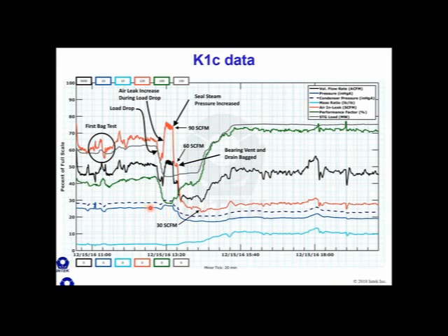And here in the blue line, you can see is their condenser pressure. It decreases as the air in-leakage decreases. You can also see that we've plotted the cleanliness factor for the unit. That's shown here in green. The cleanliness factor is 40% here. And then after the air in-leakage is fixed, it raises up to about 70%.